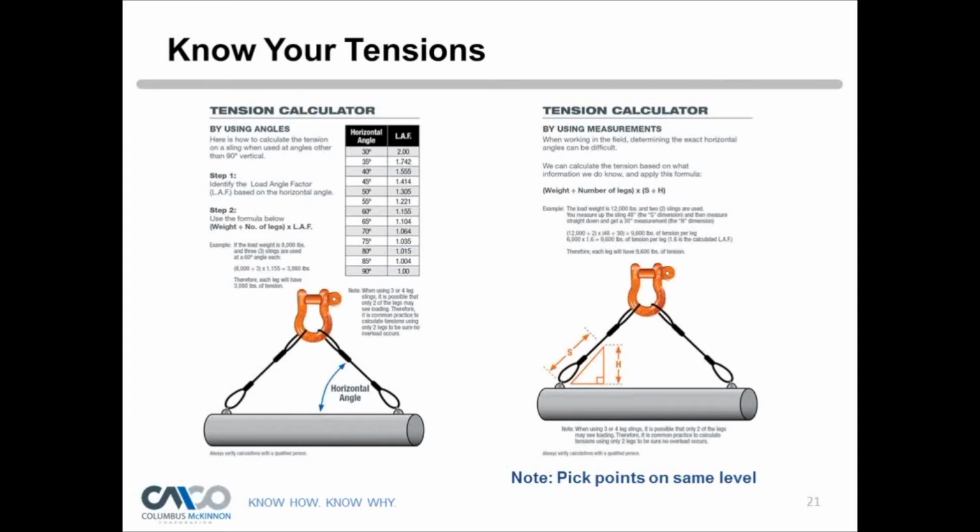And what happens when we're lifting? Sometimes you can lift some heavy loads, and depending on what your angle is, that can lead you to a larger chain size, which could cost more money, or a much bigger sling than you really want. So of course we want to try to get the lightest sling possible for somebody, especially if they're rigging. Oversizing is great, that's fine, there's nothing wrong with it. The larger the better. But on the other hand, in my opinion, why have something that's too big that you don't need? So you can try to size exact.